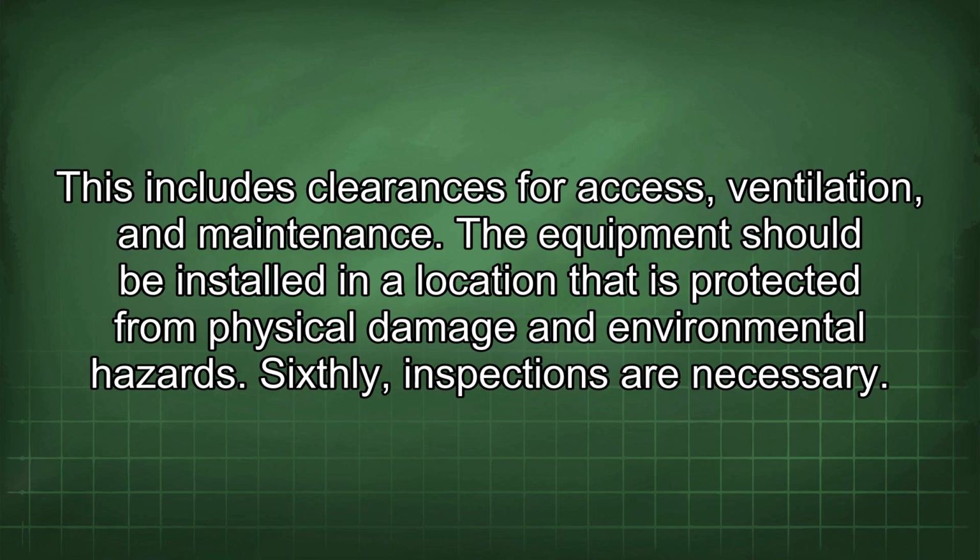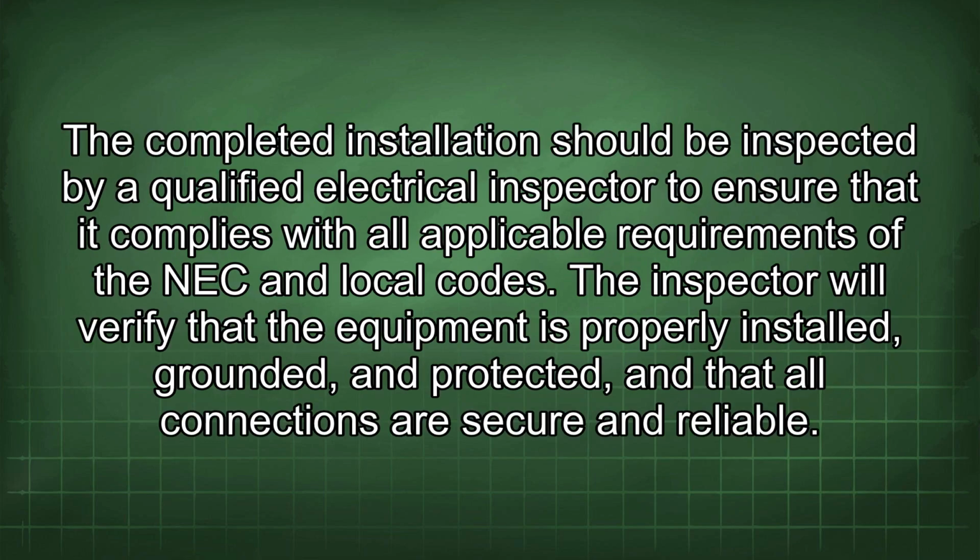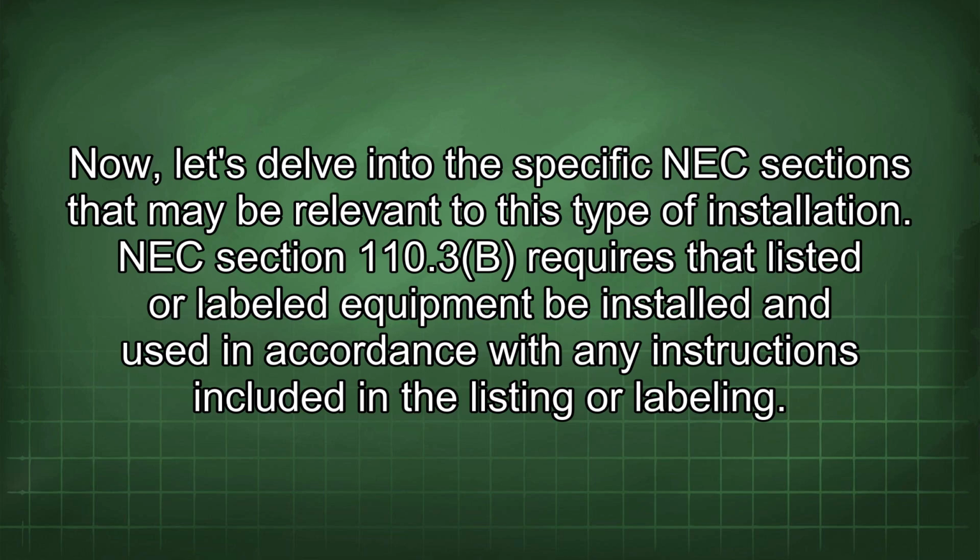Sixthly, inspections are necessary. The completed installation should be inspected by a qualified electrical inspector to ensure that it complies with all applicable requirements of the NEC and local codes. The inspector will verify that the equipment is properly installed, grounded, and protected, and that all connections are secure and reliable. Now let's delve into the specific NEC sections that may be relevant to this type of installation.